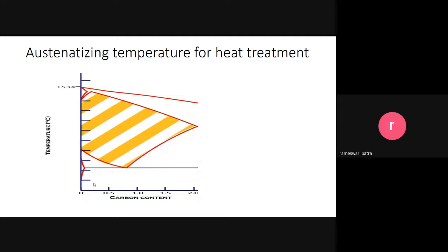So what is the property of steel now? It will deteriorate. Will strength decrease or increase? Decreased, obviously. Why decreased? Because of the more proportion of ferrite. You understood now? But if you heat the steel above A3 here and then do cooling, then what will be the phase formed from this temperature to room temperature? You'll get pearlite and some proeutectoid phase. The amount of proeutectoid phase will be less, depending upon the composition.